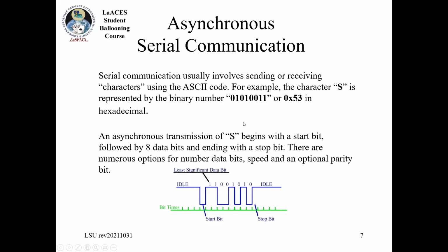And for the UART protocol, which is what the actual serial port, the one that gets sent to your computer, uses, you send data in 8-bit chunks, right? You send a single byte at a time. And in general, this is encoded using the ASCII code. So when I send this particular byte, that's actually the character S, right?